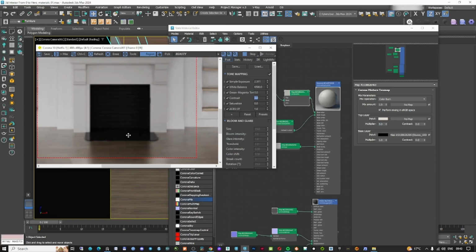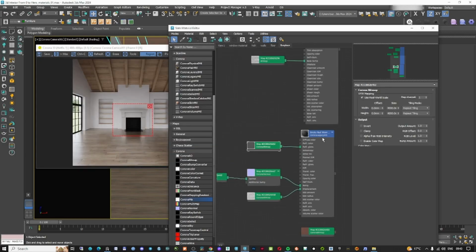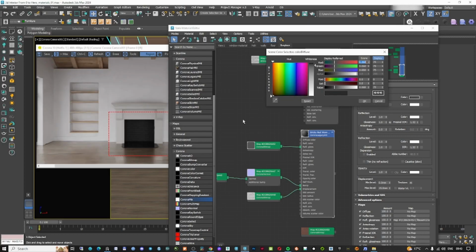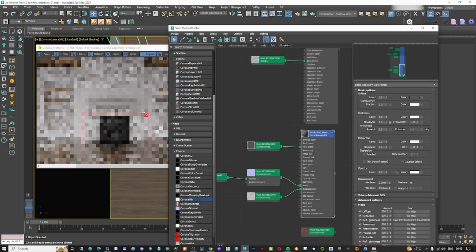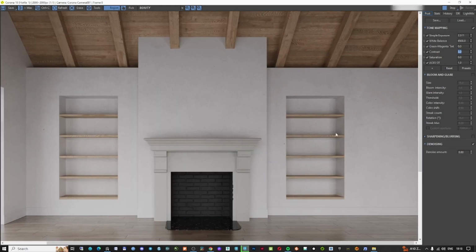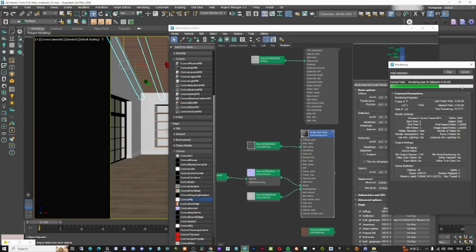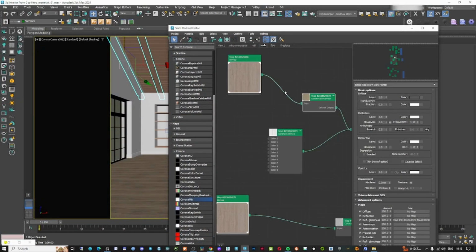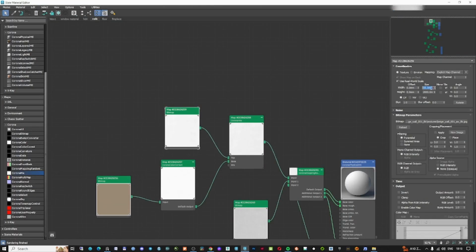And then yeah, let's make the inside the fireplace, which is this brick, a little bit lighter. It's also better. I would like to see more details in there, so I'll just leave it like this for now. Okay, so this is a first render, only with an empty space. So yeah, the texture on the wall, it's a little bit too big. So yeah, let's change that first. I'm gonna stop this. I'm gonna go to my wall where my texture is, this one, and I'm gonna change here the texture, make it 1000, make it smaller.